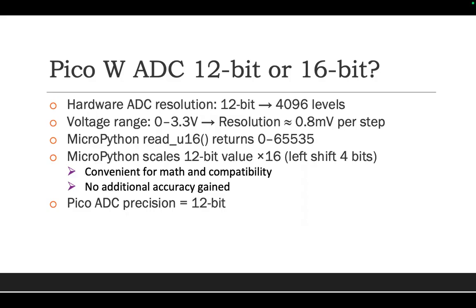Which means the resolution will be around 0.8 millivolts per step. It's not 0.0005. But in MicroPython, if you check the code, it reads like a 16-bit. It returns 0 to 65,535.